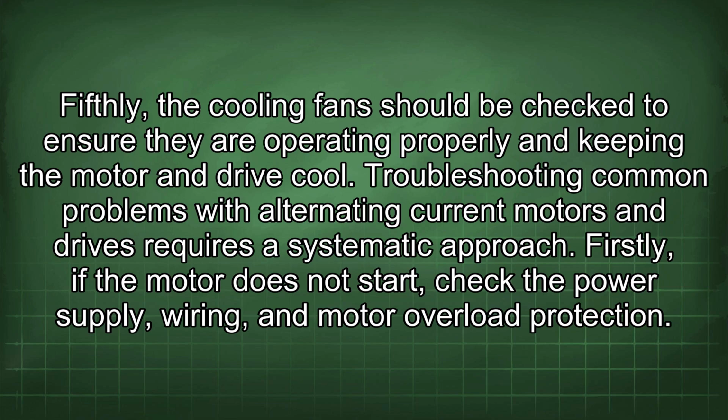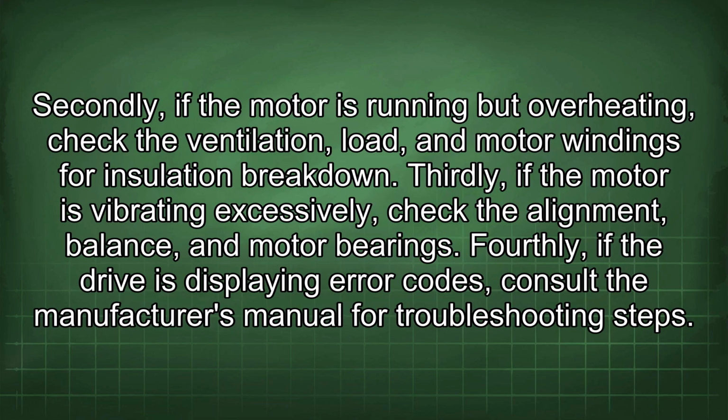Troubleshooting common problems with alternating current motors and drives requires a systematic approach. Firstly, if the motor does not start, check the power supply, wiring, and motor overload protection. Secondly, if the motor is running but overheating, check the ventilation, load, and motor windings for insulation breakdown.